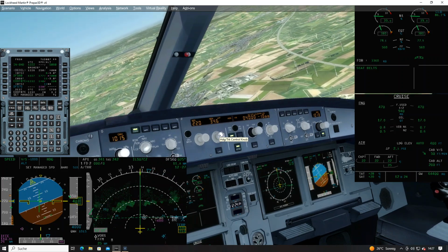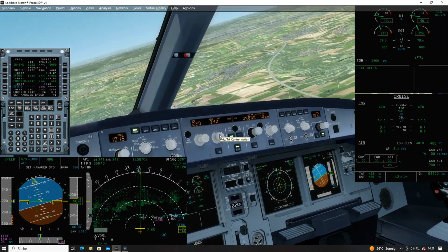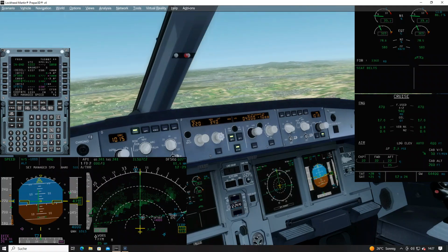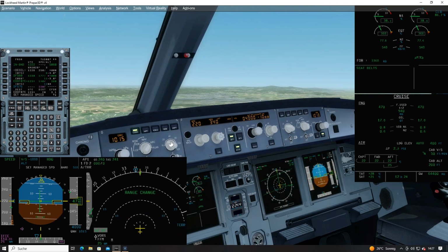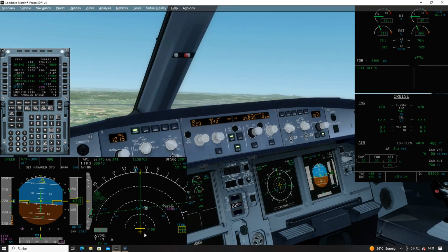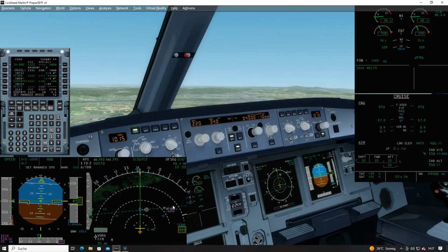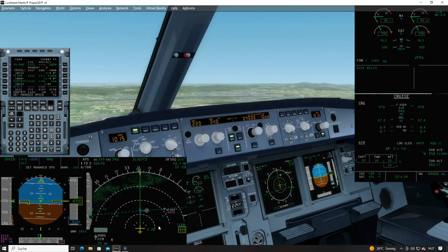I roll out on heading 340. That's why I'm not a professional air traffic controller. They can do it much better. My original heading of 040 would have led us to an intercept with the localizer course beyond Delta Fox 560, which isn't a good idea at this time. So we'll fly a little bit more towards the center line.